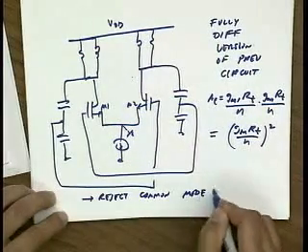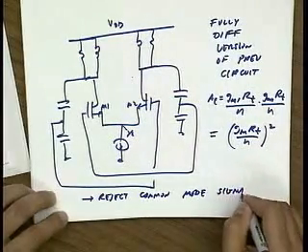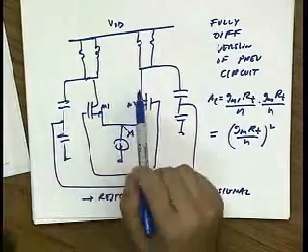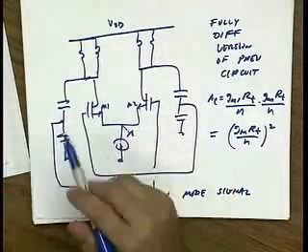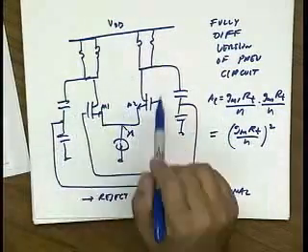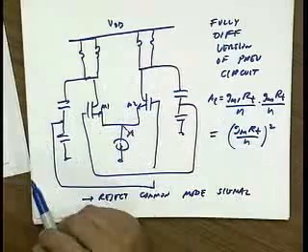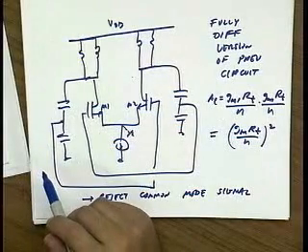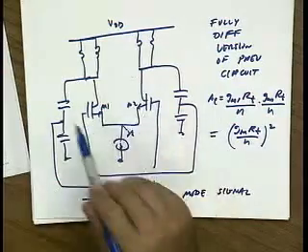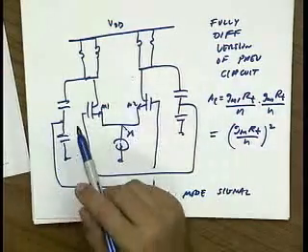The reason this is really important is that once this thing is oscillating, the actual closed loop gain is nearly infinite, right? We saw that. As the loop gain approaches 1, the closed loop gain goes to infinity because we have positive feedback. As we'll see next lecture, it's actually not infinite gain, but a very high value of gain.